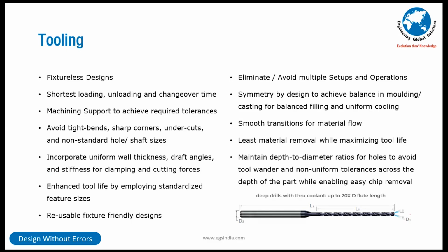What do I do about this? Sir, multiple setups are required because I'm having multiple datums. Why are you having multiple datums? Because my assembly sequence has multiple sequences of assembly. Integrate components, make fewer parts, keep the assembly simple, reduce the number of setups. I gave you the answer as well. Symmetry by design to achieve balance in molding, casting for balanced filling as well as for uniform cooling. No brainer. Smoother transitions for material flow.